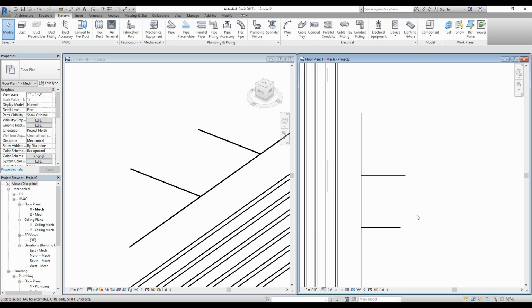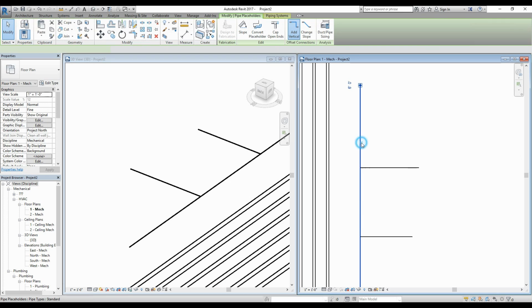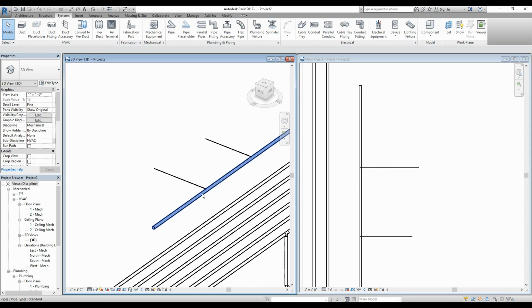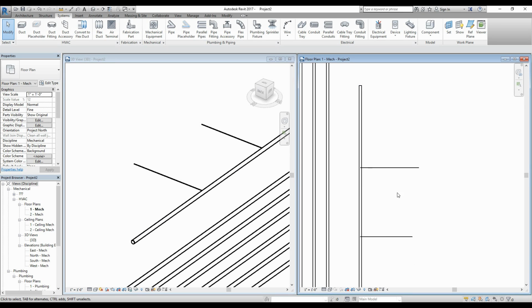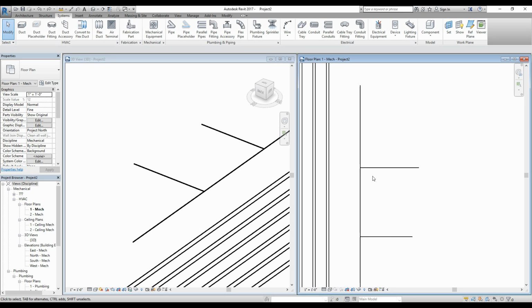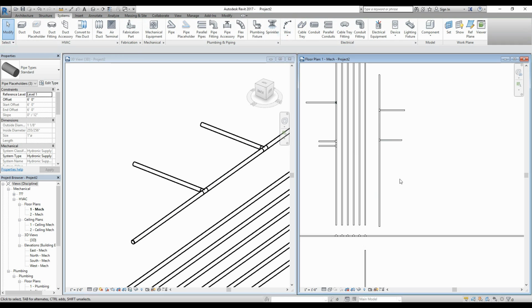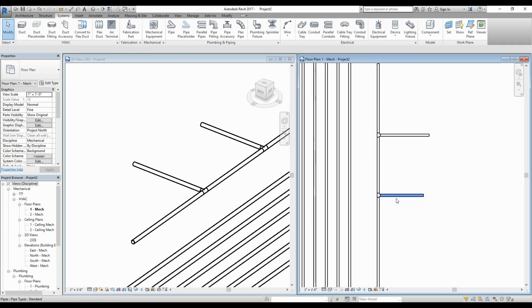But you may be thinking, wow, that's good and well and all, but what if I want real pipe? Well, there's a solution to that. You can click it and convert it. Now you get real pipe, and it just popped up with the error saying it has output connection. That's because this is a placeholder and that's a pipe. What we can do if we want to convert all of them is hover over this pipe, press tab, and it'll select our entire branch. And now we can convert it, and it'll convert everything and put in the proper fittings.